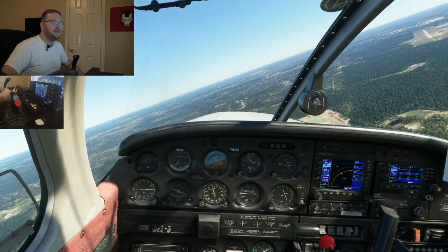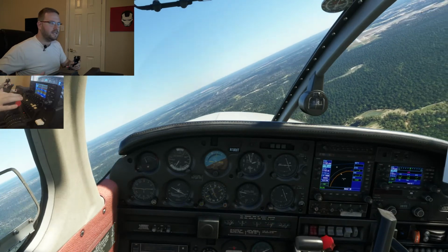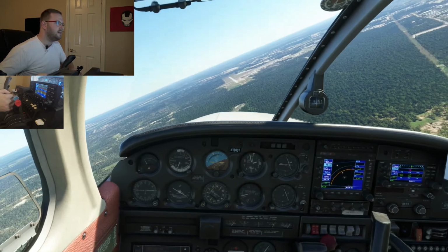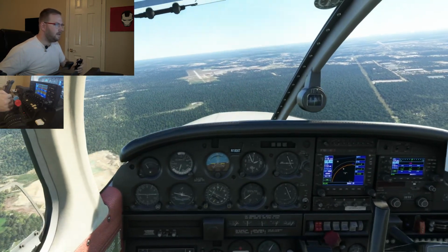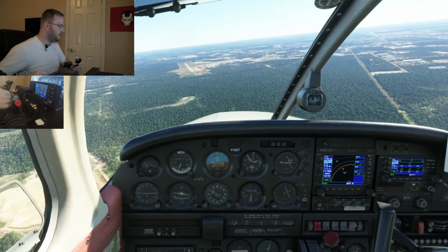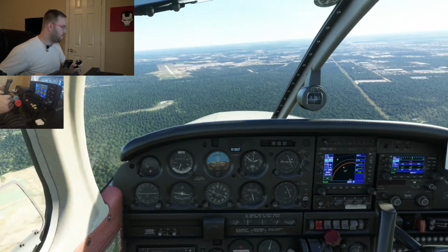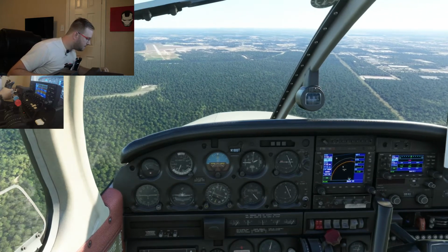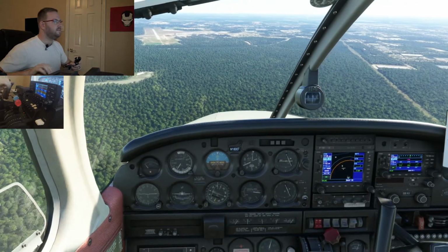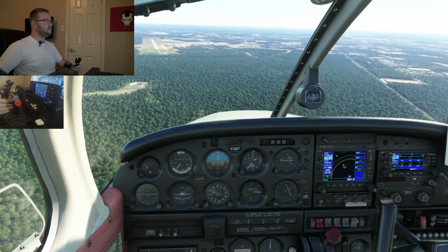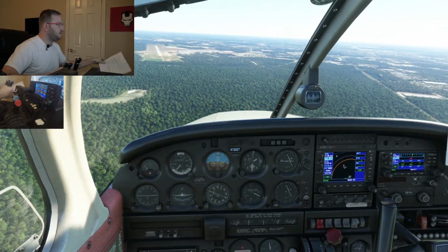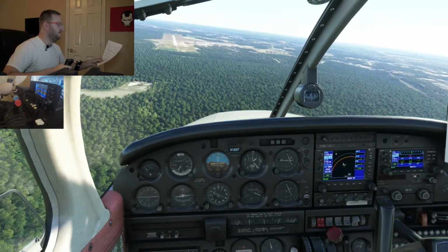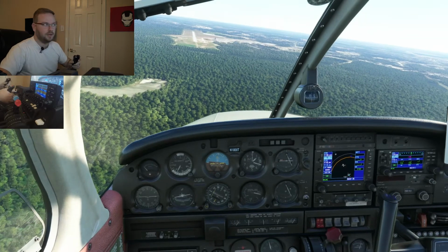Now I could be tuning my GPS, but instead I can already see the airport, so why tune my GPS for the diversion? So they cleared us in, and we're going to start our descent now, getting down to pattern altitude. Pattern altitude, by the way, here is 1250, so we're still pretty high and pretty fast. So the diversion, by the way, divert to new airport, identify nearby airport, either perform a touch and go or go around at that airport. So that's what we're going to do.